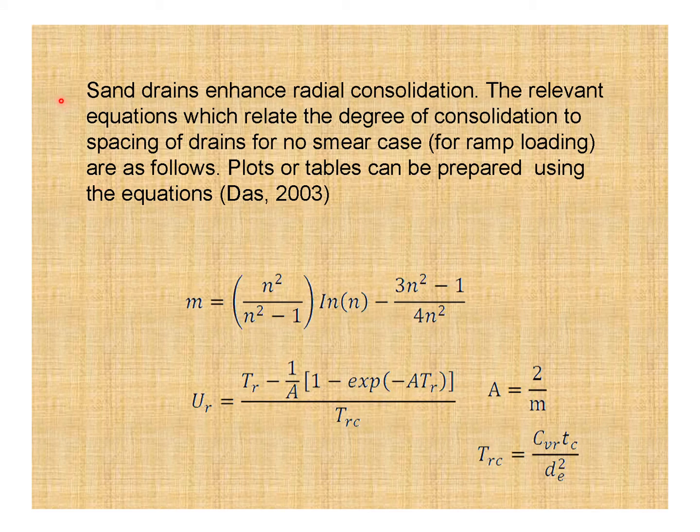Sand drains enhance radial consolidation. The relevant equations which relate the degree of consolidation to spacing of drains for the no smear case, that is for ramp loading, are as follows. Plots or tables can be prepared using the equation. So look at the formula for M, and then U sub R, and then in this formula A is equal to this and T sub RC is equal to this.